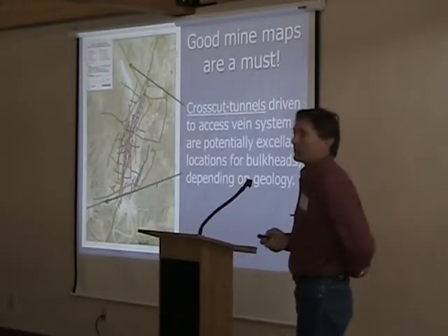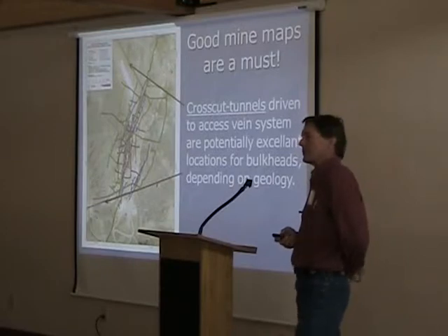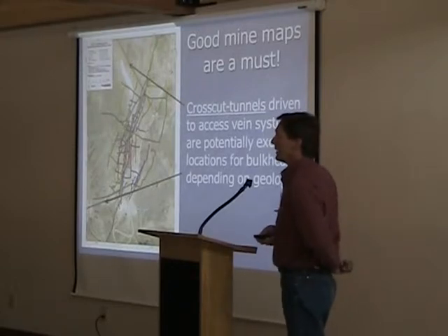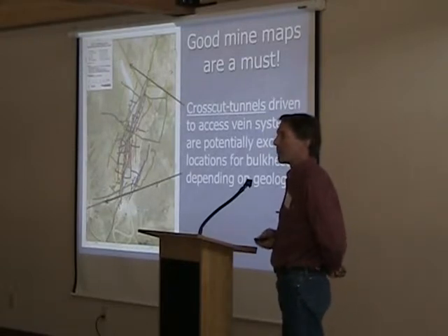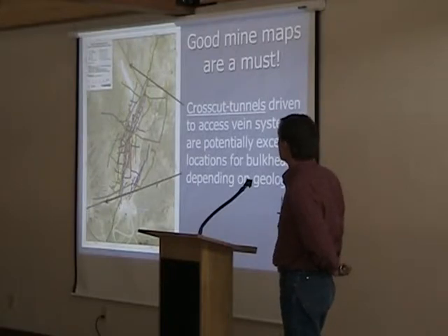The mine maps are a must. If you don't have really good mine maps, if there's not really good understanding of what's going on, it makes the job that much more difficult because you're really just guessing. You really probably can't spend enough money on drilling to figure out what's going on. And so again, mine maps are just key to knowing where to be and what to look for.